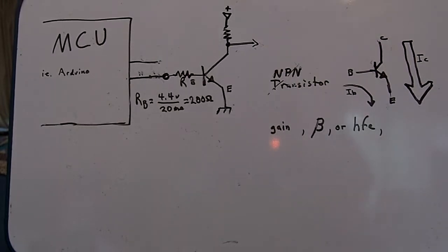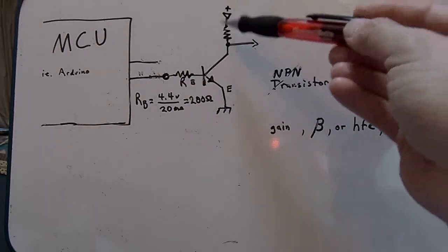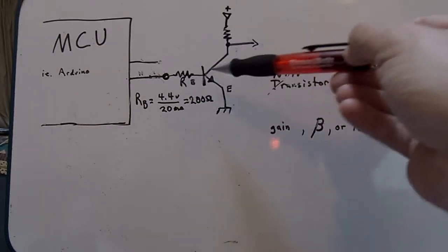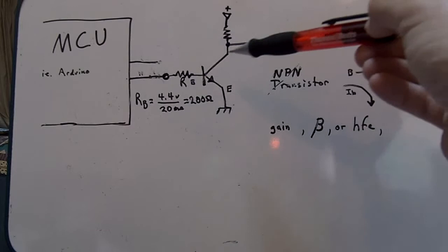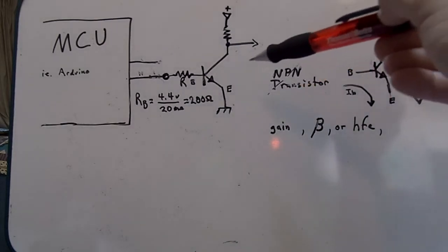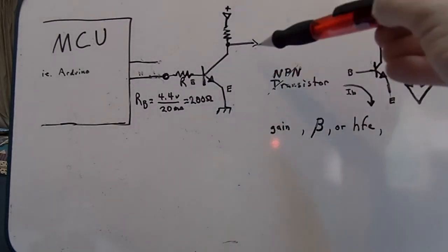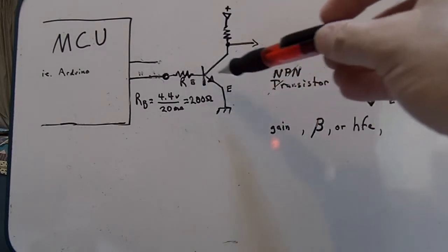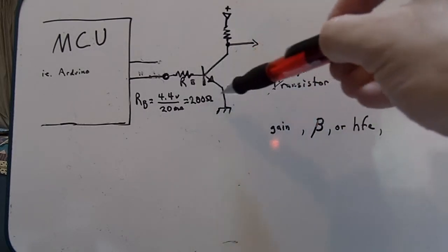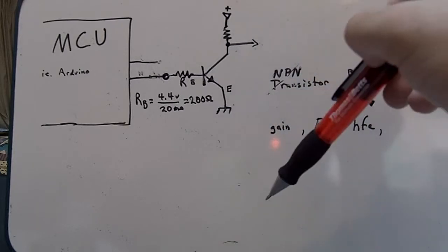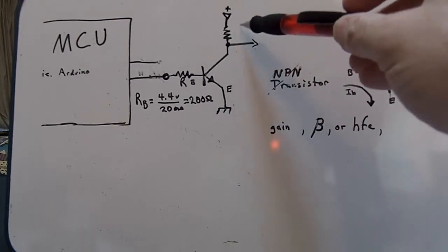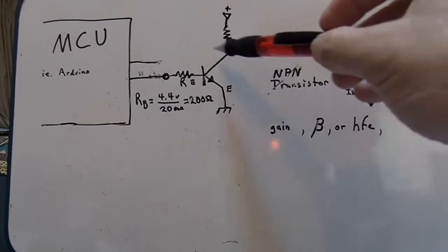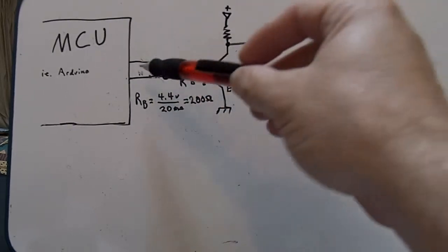But now we're getting a little more esoteric and complicated, but I just wanted to go through a pull-up resistor and how it regards to a transistor circuit, because this is very common in audio, this type of stage. But we're looking more or less to turning things on and off at this point. We're not looking at audio. But this is very much how a simple audio stage might be set up, very commonly. Again, a pull-up resistor, and we're reversing the phase. We're going from a high to a low, or a low to a high.